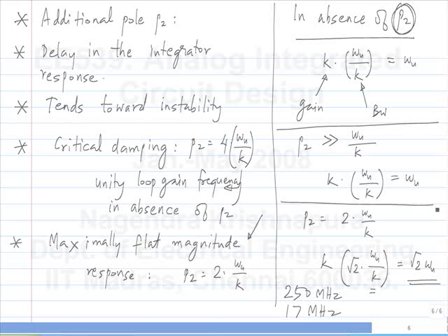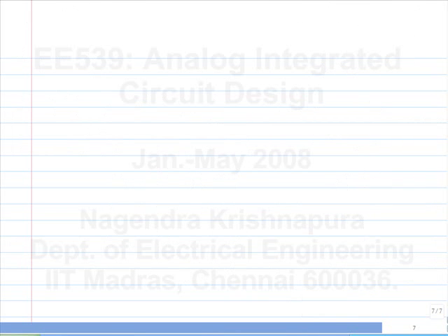Dominant pole. How do you use that? Let's say I know that I have some P2, P3, P4, and from these values, without solving the 4th order equation, I want to judge the response. How will I do that? Choose the smallest pole. That is one way. If P3 and P4 are much more than P2, I can probably do that. But let's say that's not the case. They are somewhat comparable. If it was very large, I would have done that. That's correct.